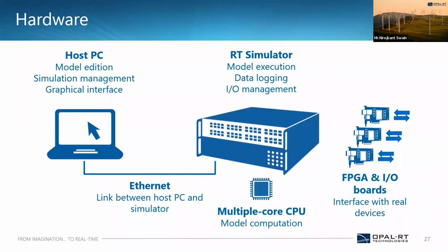How does the OPAL-RT real-time simulator work? First, you need to design your model on the host PC. For communication between the host PC and the real-time simulator, we use Ethernet or TCP/IP communication. This is your Ethernet.